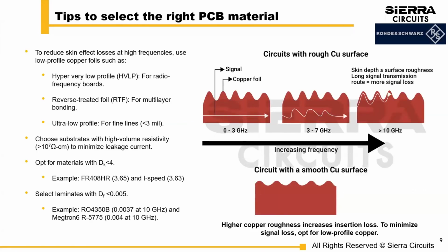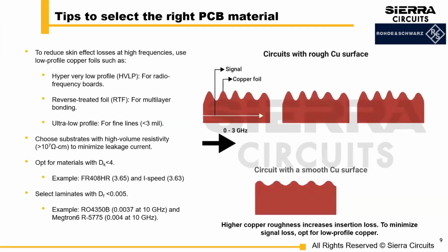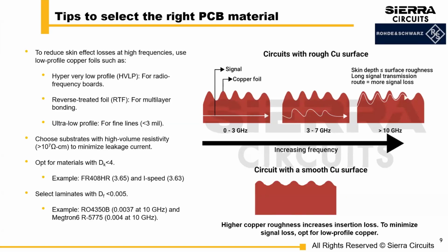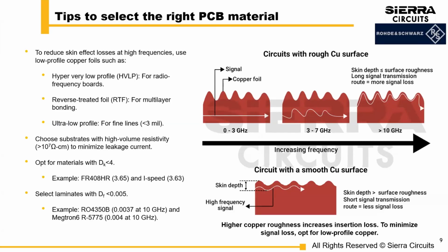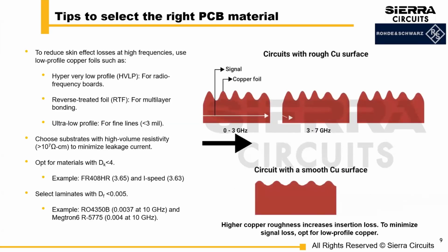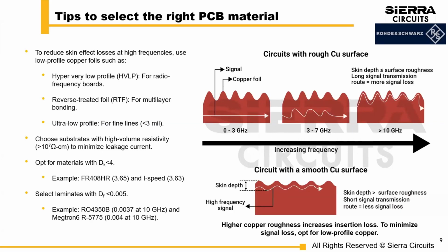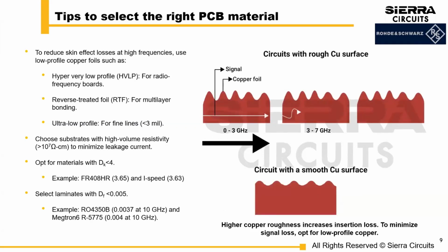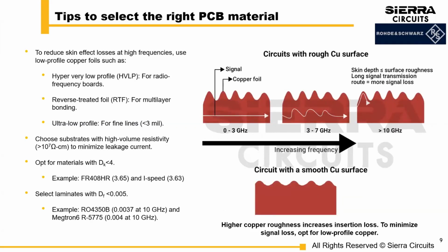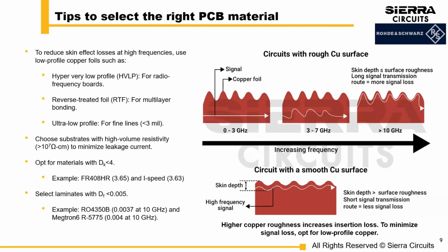There are lots of materials around the world, and I think US manufacturers are becoming more accustomed to the overseas materials, so check with your manufacturer if they have experience with that material. Knowing the process steps of a material is critical in order to build a good circuit board. Anyways, I digress. So we want to first reduce the skin effect losses at high frequencies.